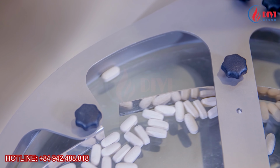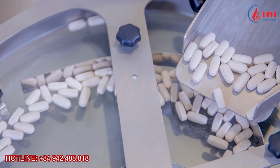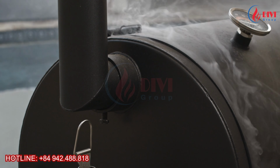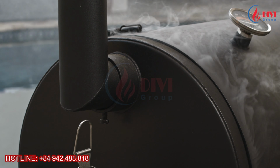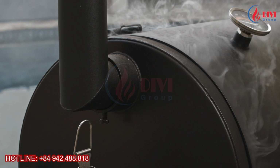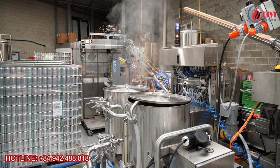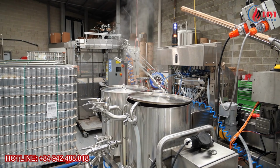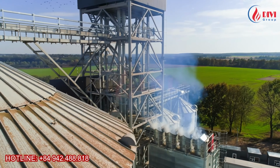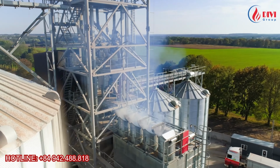This is especially important in the food, pharmaceutical, herbal, fruit juice, and coffee industries, where preserving vitamins, nutrients, aroma, and color is essential. Excessive heat can damage or destroy many valuable components in the product. Vacuum evaporation removes water at much lower temperatures, helping maintain superior product quality. This is one of steam's most valuable applications, yet it's often overlooked.